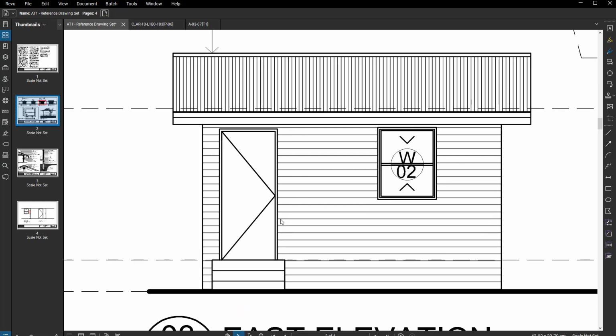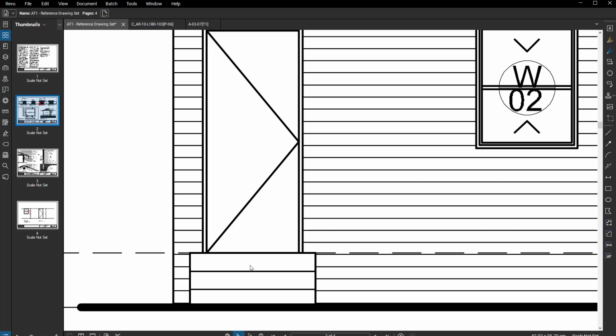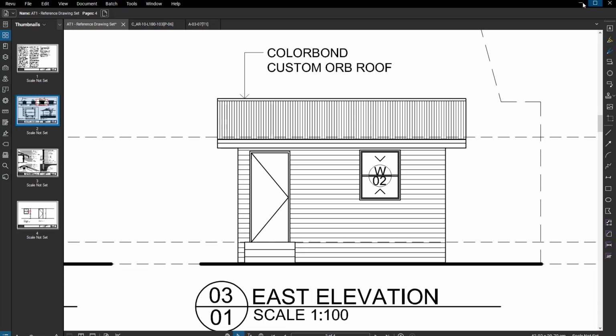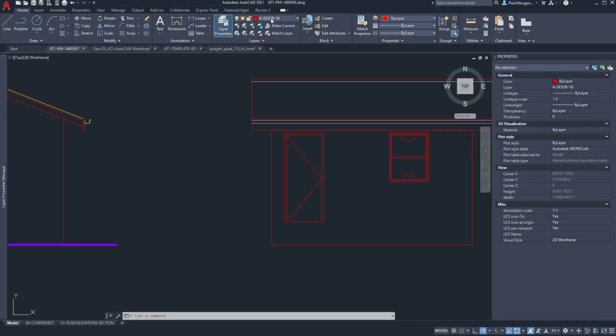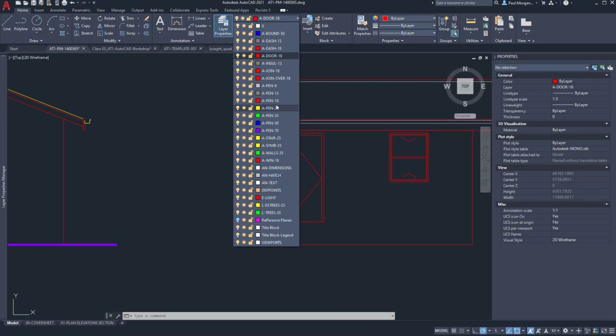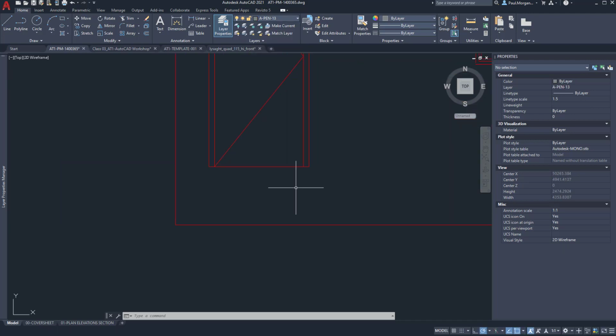The last thing to do is to add in the stairs. So the ground, stair 1, stair 2. So let's go back to AutoCAD. I'm going to use a different pen for this. I'm going to use pen 13. And I'm going to start off by just going from here straight down on both sides, just to the line. I'm going to then do a polyline. I'm going to come out, say, 18 mil, and then down, same on the other side, across 18 mil, and then down.